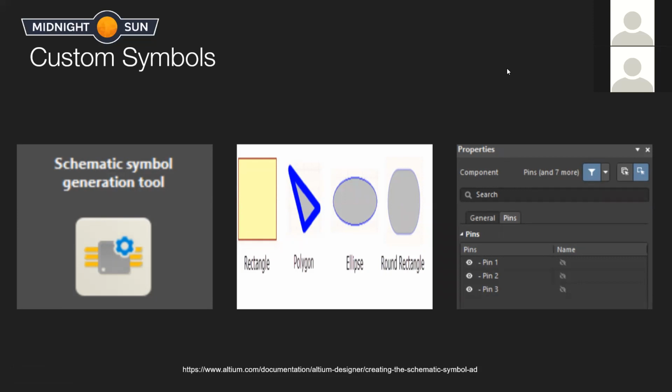If your component doesn't have any symbols, you might need to make it yourself. We do have general best practices on Confluence, I believe, for making schematic symbols. If we don't have it up anymore, there's lots of good documentation online for how to make your symbols standard. You want to make it easy for people to understand what it is. Generally, you'll use rectangles and then pins coming out. You'll label the pins from 1 and then however many pins you have.